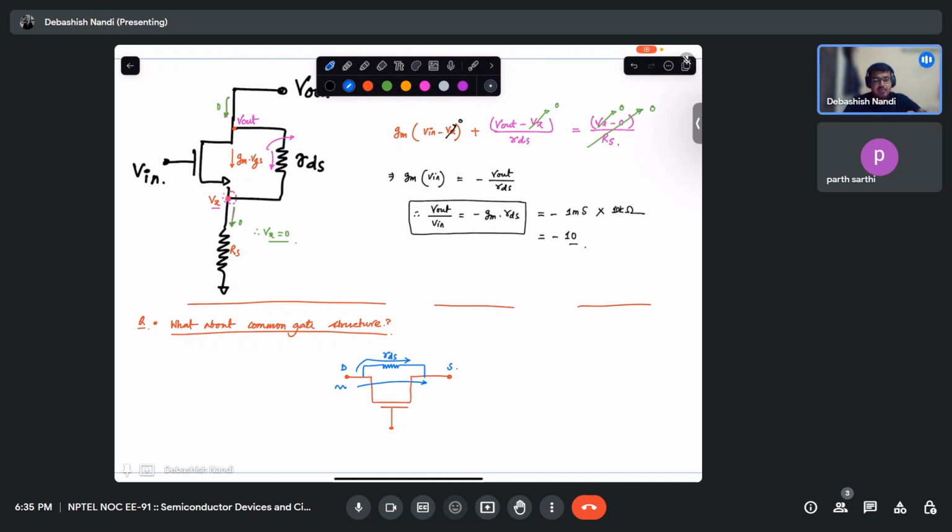See, the way to go about the problem is you draw the small signal equivalent. You then take multiple nodes, and you will find out the relations, how the currents are flowing. If some currents are to flow through RDS in a particular structure, it will flow. What is the issue in that? For this particular problem, RS is not important. It is not sacrosanct, okay?